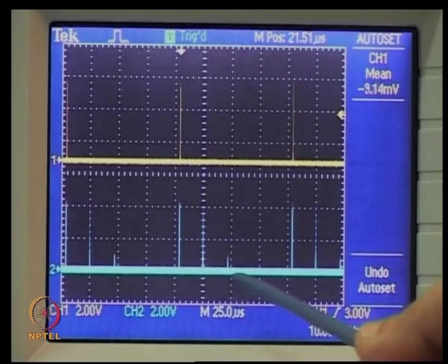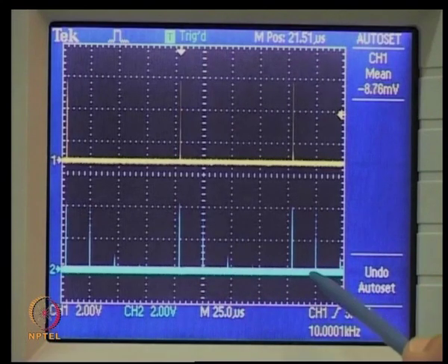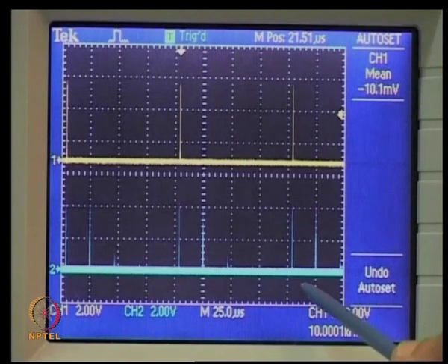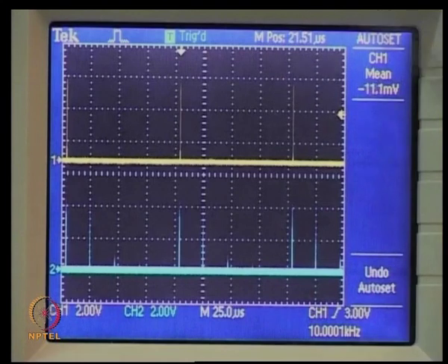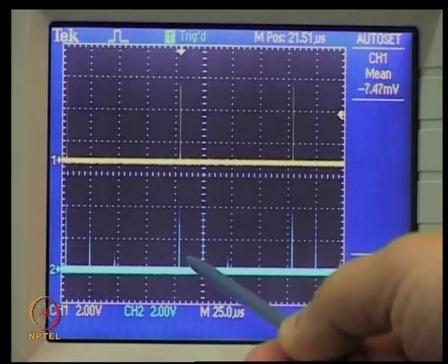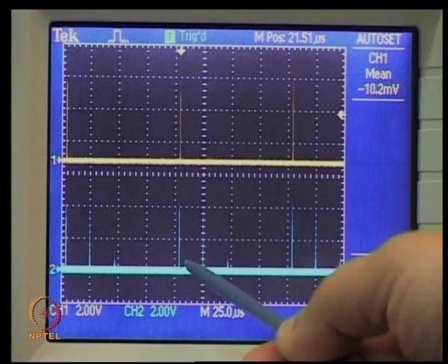Now in channel 2, we can see that there are multiple peaks, each with diminishing amplitude. This is because after each pass of the signal in the 4 km fiber, we get some of the power at the receiver and some is again coupled to the fiber.